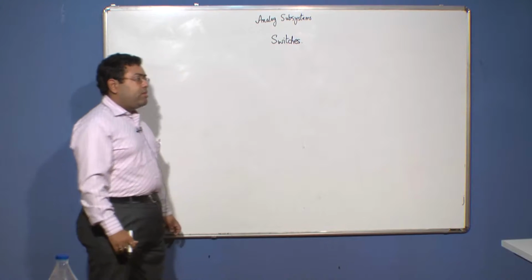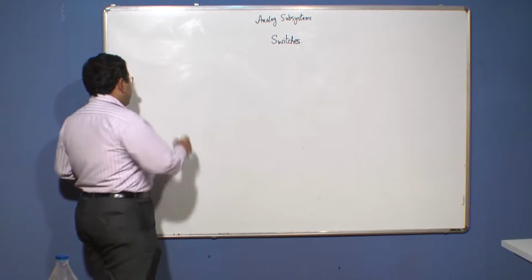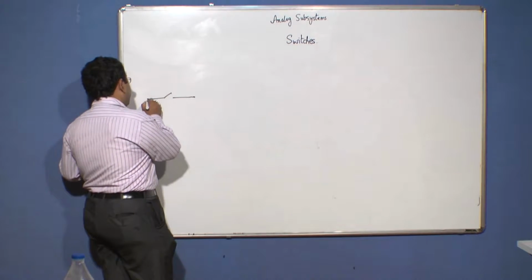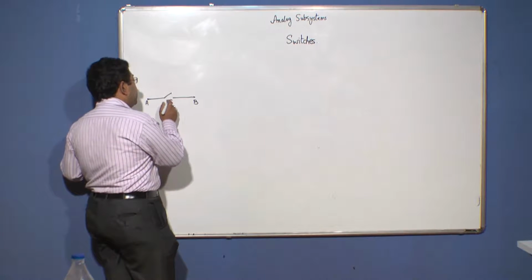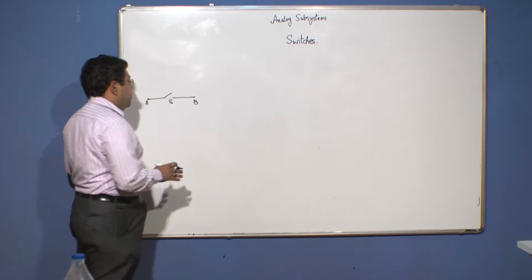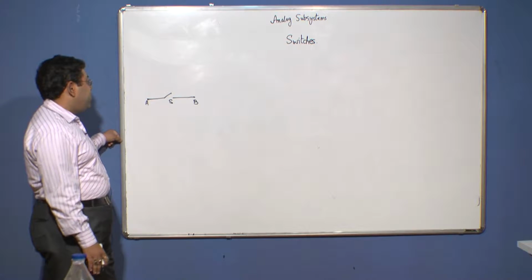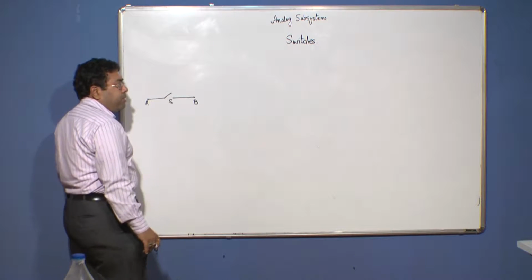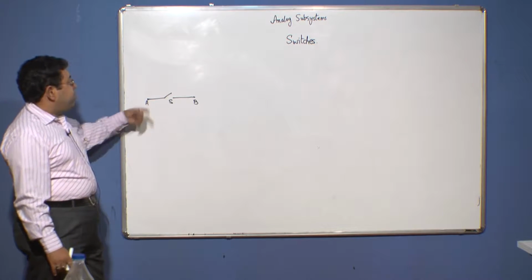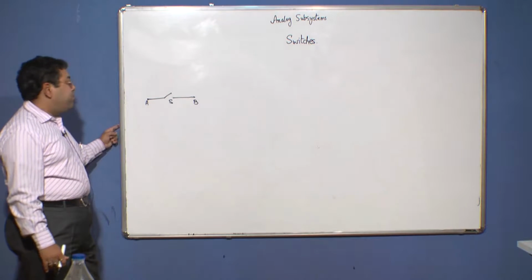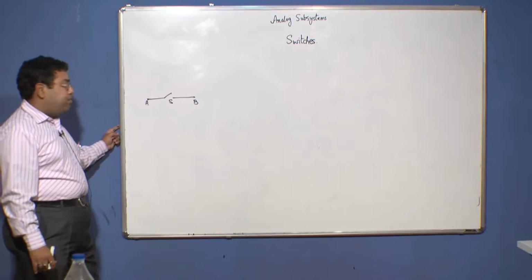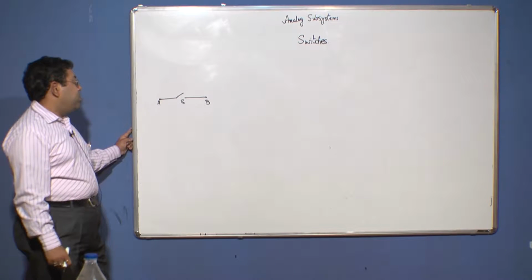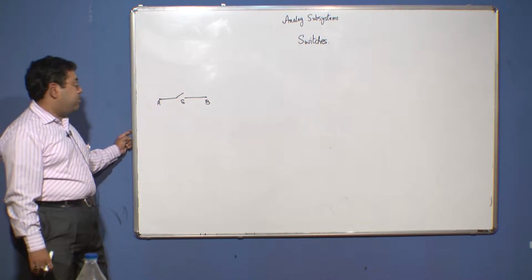The important circuit element is a switch. A switch is basically a two terminal circuit element such that there are two states, the on state and the off state. When a switch is on, it should provide a short circuit between its two terminals. On the other hand, when a switch is off, it should provide a perfect open circuit between its two end terminals. So, a switch is basically used to open or close a link between two terminals in a circuit.